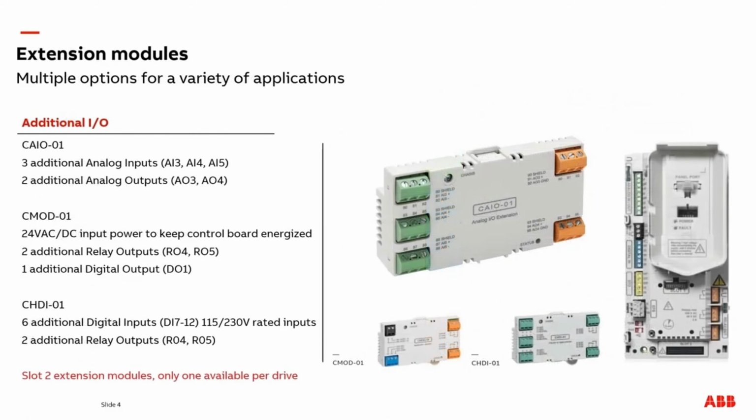If additional I/O is required for your application, several different extension modules are available for the 580 series of drives. There is only one slot available per drive, so only one extension module can be used at one time.